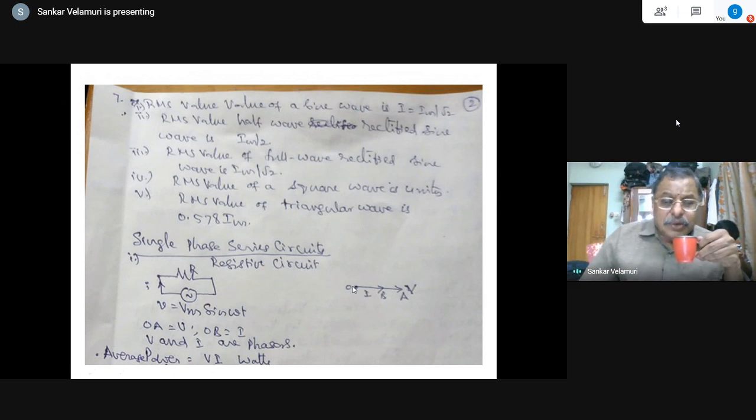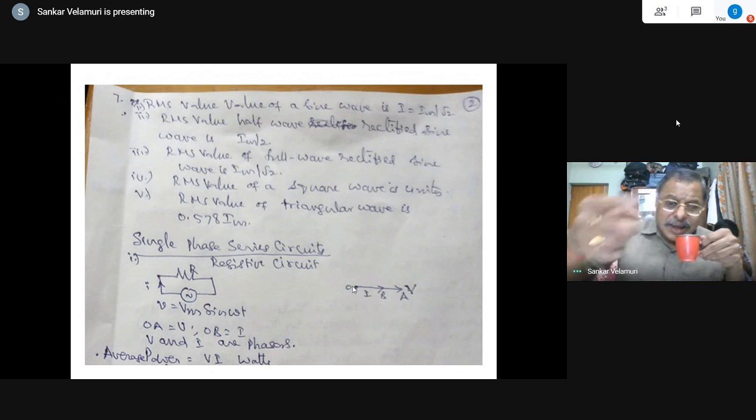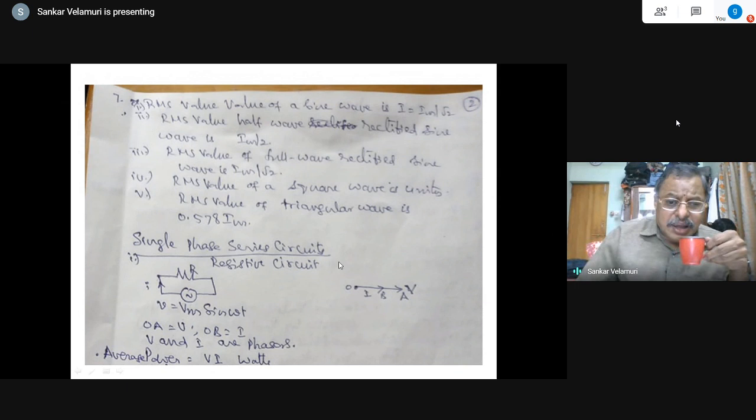Just as one sine wave is obtained, correspondingly the phasor rotates through one cycle of revolution through the 4 quadrants, so 360 degrees. Therefore, a phasor is represented as a vector whose one rotation is equivalent to one cycle of the EMF that is being generated or one cycle of the current, because it is an alternating current quantity.